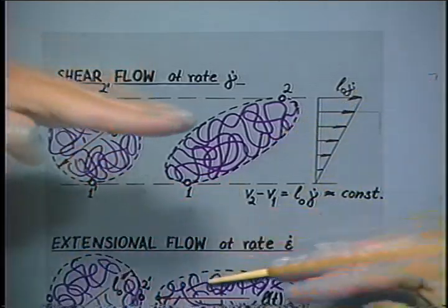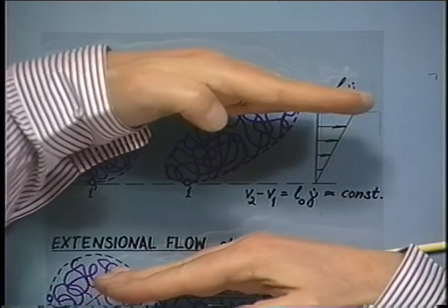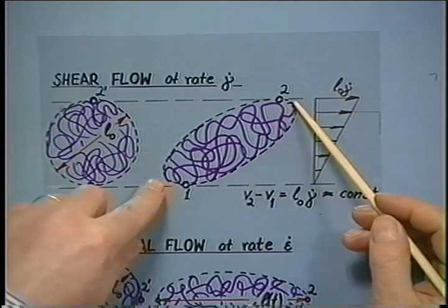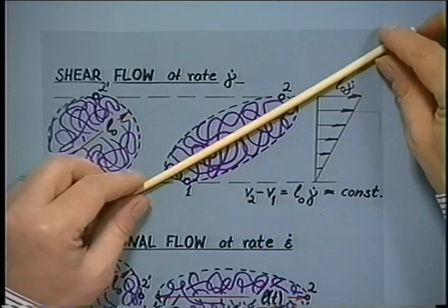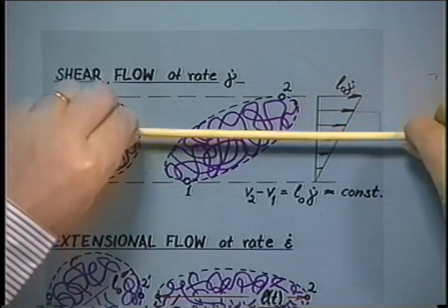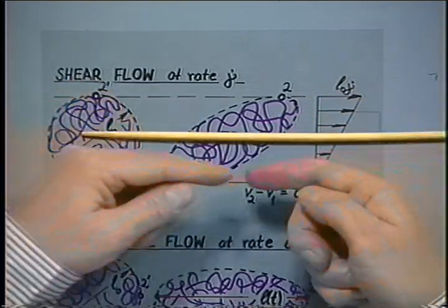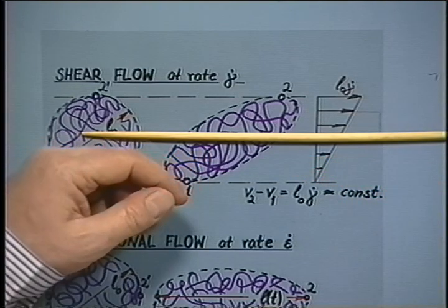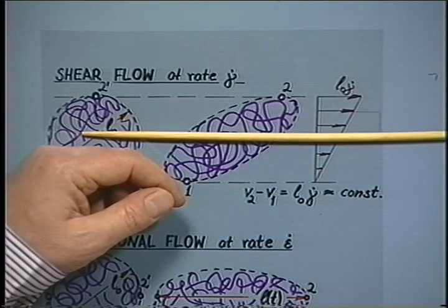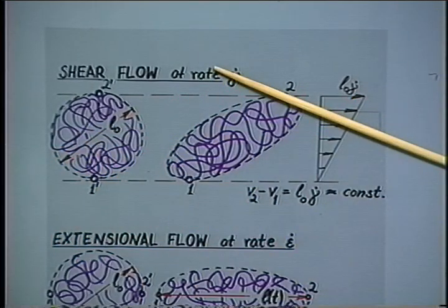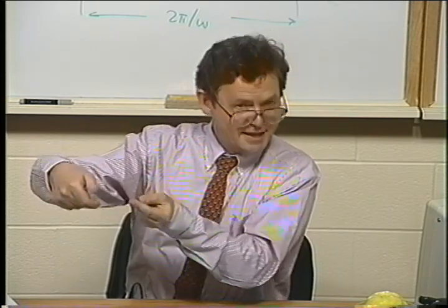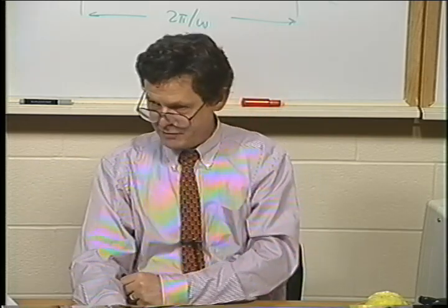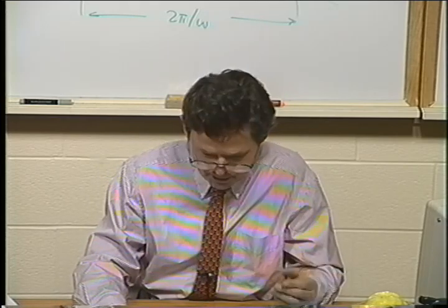So for producing this flow, we are shearing in this way. But the molecules, now they want to go back to their random state, and they will give rise to a tension in this direction. And this tension then has a projection in this direction. There's a tension in direction of our shear flow, which is quite amazing. People discovered that. I think Weissenberg discovered that in the 30s. He sheared a material, applied a shear stress, and he found that there's a tension along the direction of flow, tension in the material in the direction of flow. And that's quite surprising.